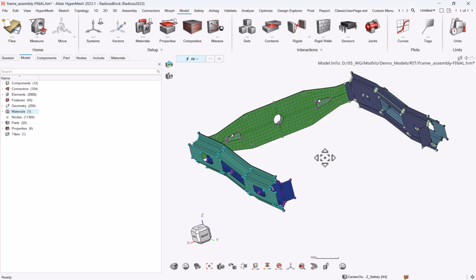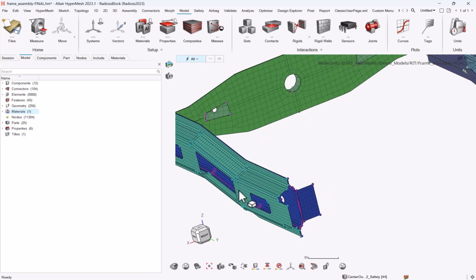First option is to have a second mesh, which is dedicated to the stamping analysis with the original shape of the blank of this part, for instance. And we define the tools, we define the velocity or the displacement of the tools, and then we run the full computation, generally with explicit schemes. And once we get the results, we map the results from the stamping simulation on the mesh for the crash simulation. Not the most straightforward approach.